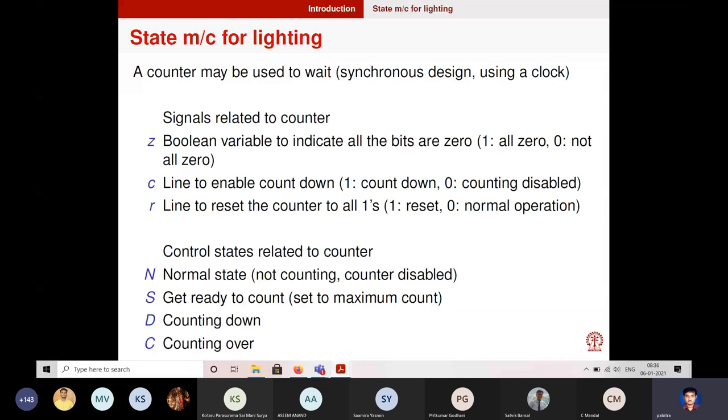So this counter changes state only every millisecond. The state change cannot happen in between. It cannot happen at 1000.12 milliseconds. It happens at 1000 milliseconds, and the next time the counter changes state is at 1001 milliseconds. Nothing happens in between. If the state changes happen only at 1000, then 1001, then 1002, then 1003, we say that this counter is synchronized with a 1 millisecond clock, a clock which changes state every 1 millisecond.